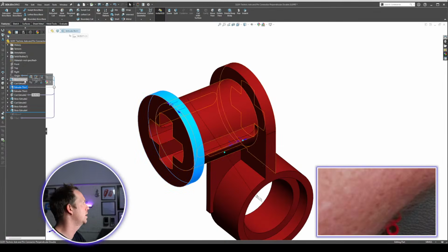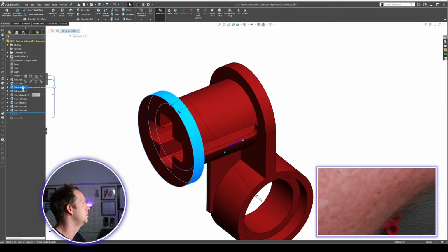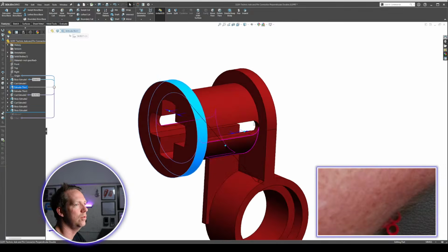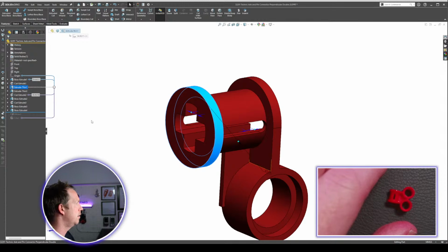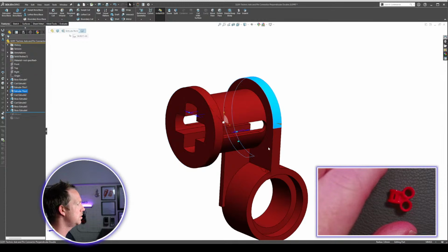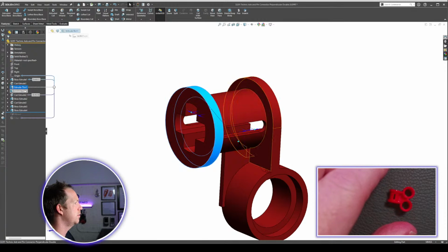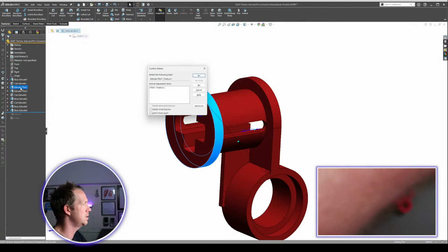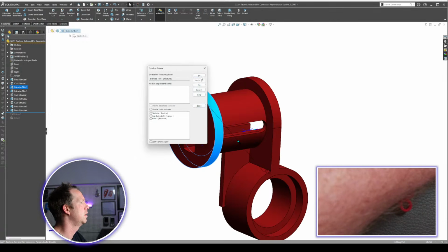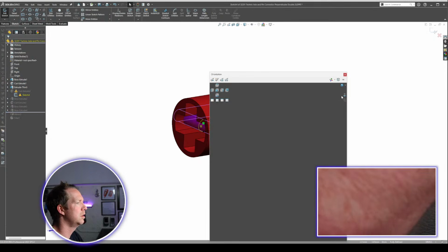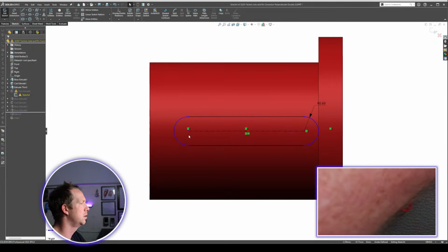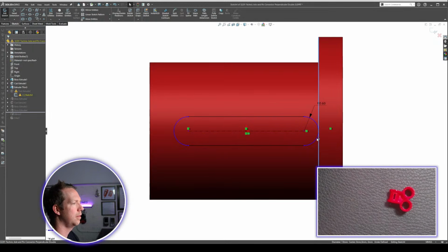But you know what? Now that I've got it here, it shows me there's a few things that I could have done more efficiently in this model, which would include not doing this extrude twice, knowing now that I'm going to mirror it. All I'm going to do here is actually just delete this one and update this sketch. That tangent.